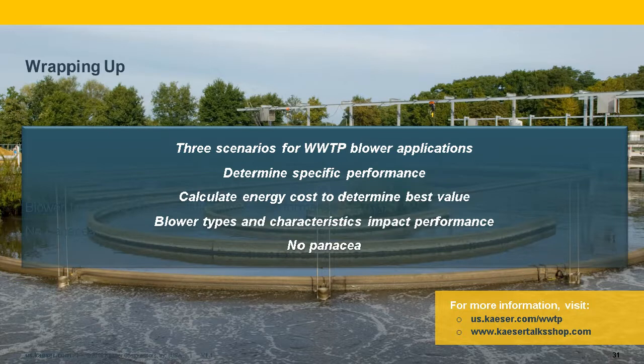We also have one here that's asking for some differences between types of blowers. It sounds like, does a twisted lobe blower behave like a lobe or a screw blower? Well, the twisted lobe is a bit of a mix of the two. There are different types of twisted lobes out there. There are some where the inlet and discharge ports are arranged directly above one another. The advantage here is the increased sealing strip, which reduces the slip through the blower, which does improve it, but it very much behaves like a lobe-type blower.